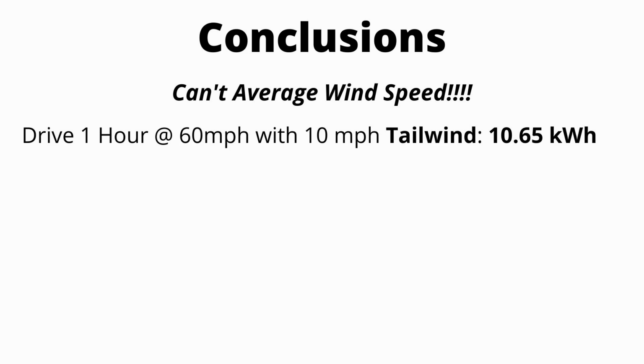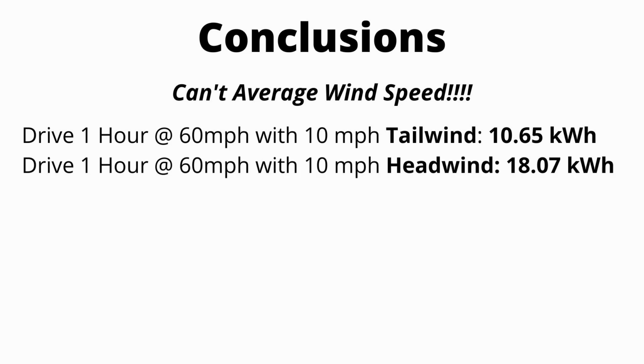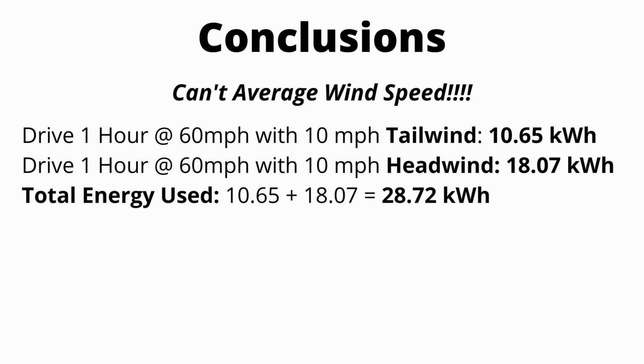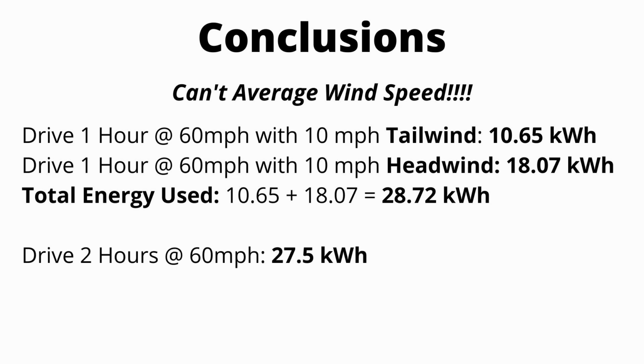You use 10.65 kilowatt hours of energy, and then you're going to turn the car around and go the exact opposite direction. So now you have a 10 mile an hour headwind. And that takes 18.07 kilowatt hours of energy to drive for that distance. And if you sum up the energy used to go there and back, it's 28.72 kilowatt hours. If you compare that to just driving for 2 hours at 60 miles an hour with zero wind, that's only 27.5 kilowatt hours of energy.